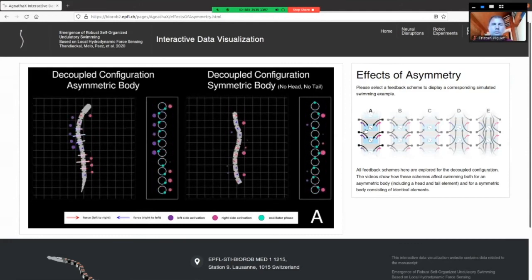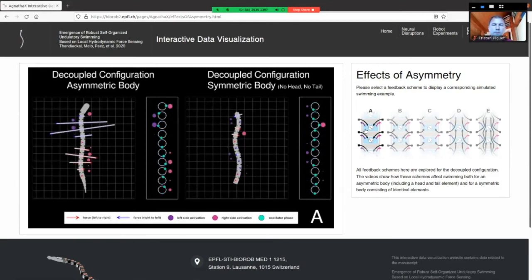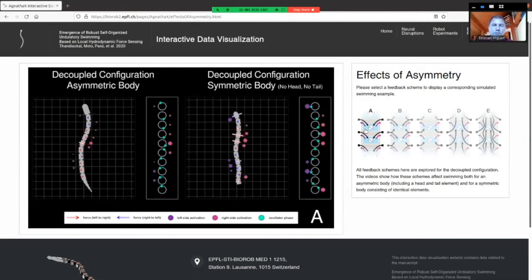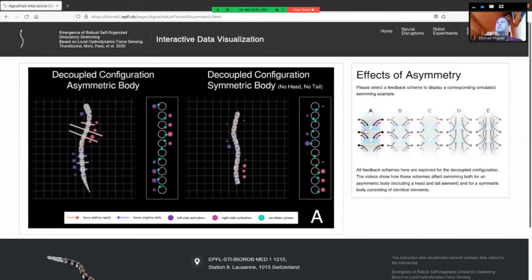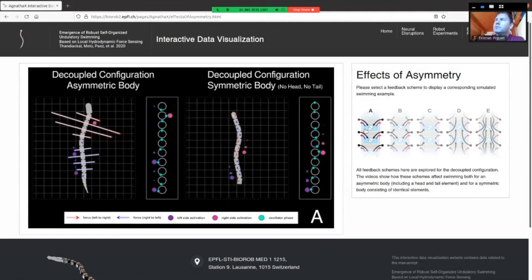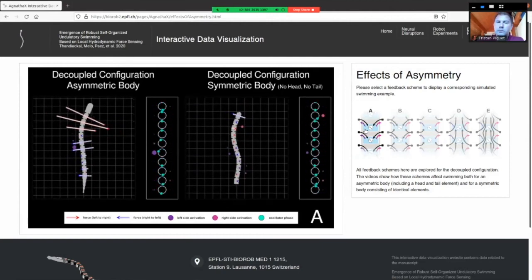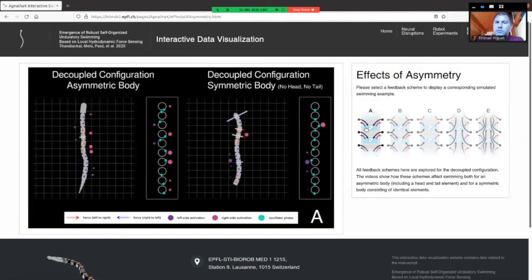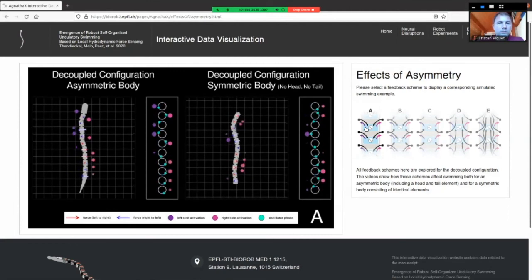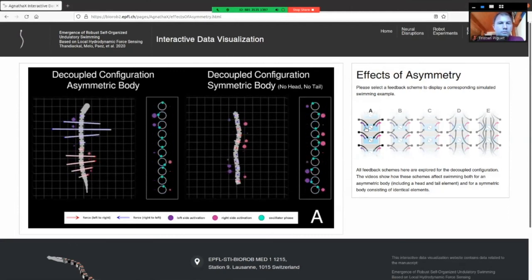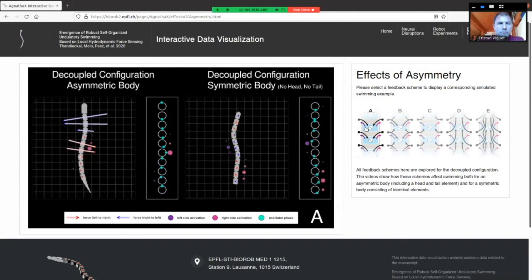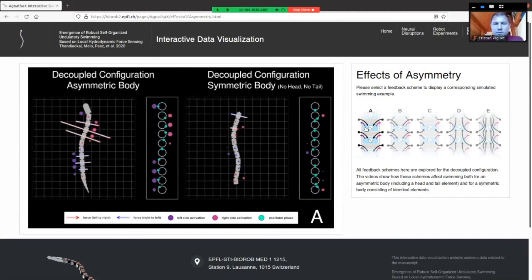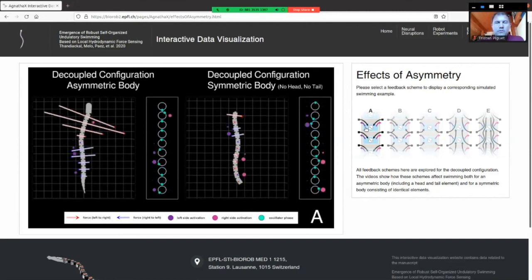And okay, this asymmetry, now let's go to this side. I hope I don't confuse people, but when you are activating a joint, actually your muscle comes before, so we have the muscle and after we have the joint itself. So basically what we are doing here is this. Before, we used to have the feedback on the same oscillator. Now we are saying that the oscillator is in the segment before, okay? So the segment before has the feedback, and this feedback is moving the segment after. This is based on what we see in muscles, is what I'm telling you.